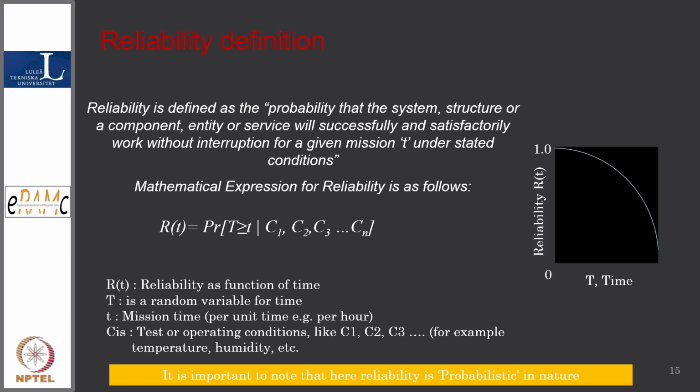So we have this expression, and here I wanted to highlight that reliability is reducing the moment the component is started. If the component is not started, reliability is 1. The moment the component starts functioning, its reliability continuously comes down because of wear, tear, oil condition if it is a pump, so many things. If you maintain it well, then the curve can go like this further.